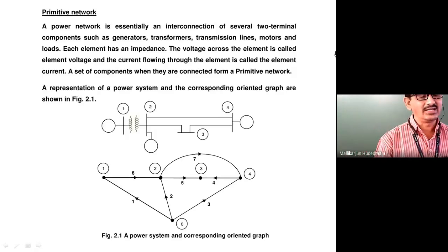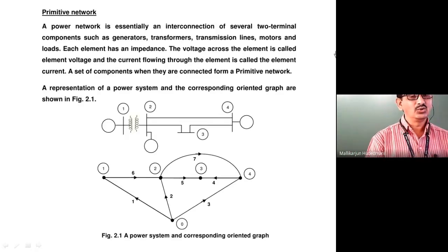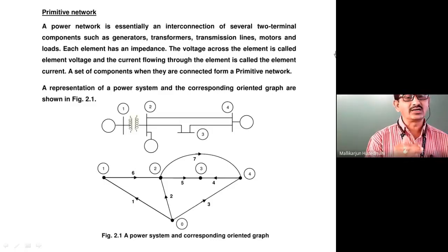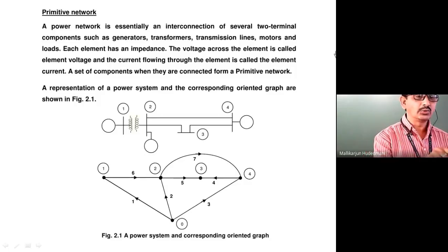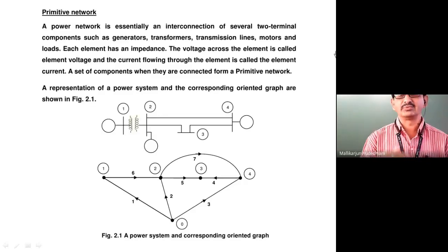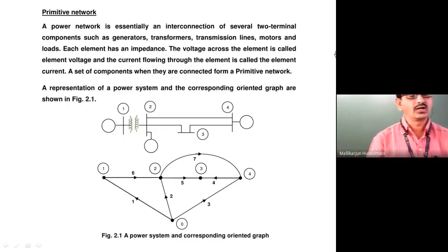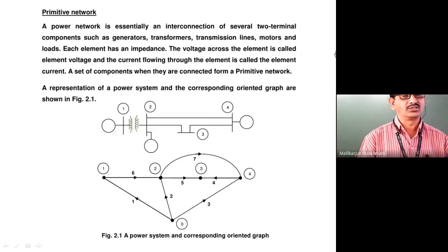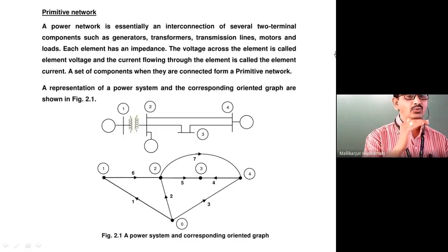In this case, I never pronounced that 0 is the reference. Usually, the first number we begin with, if it is marked as 0, is treated as the reference. Unless it is said that the 4th is the reference, 0 is the reference here. So it need not be 0 all the time. It can be anything: 1, 2, 3, 4, 5, and the author may say take 5 as the reference, then 5 must be treated as the reference. In this case, as per the representation, 0 is considered the reference. With 0 clipped off, we get 4 physical buses, the distinct principal buses.